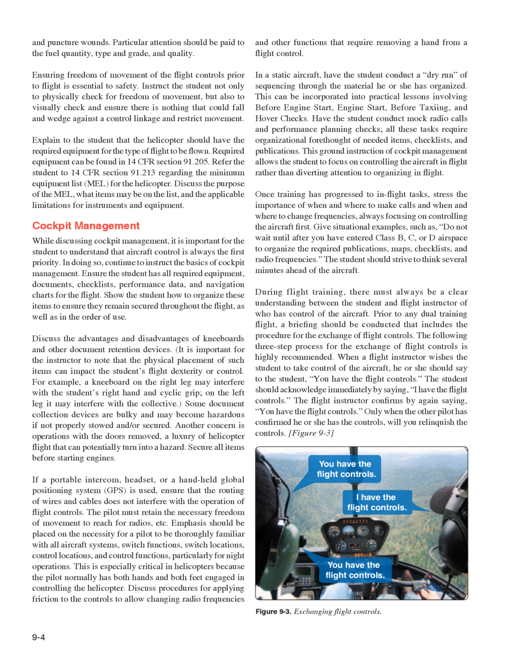If a portable intercom, headset, or a handheld global positioning system, GPS, is used, ensure that the routing of wires and cables does not interfere with the operation of flight controls. The pilot must retain the necessary freedom of movement to reach for radios, etc. Emphasis should be placed on the necessity for a pilot to be thoroughly familiar with all aircraft systems, switch functions, switch locations, and control functions, particularly for night operations. This is especially critical in helicopters because the pilot normally has both hands and both feet engaged in controlling the helicopter. Discuss procedures for applying friction to the controls to allow changing radio frequencies and other functions that require removing a hand from a flight control.